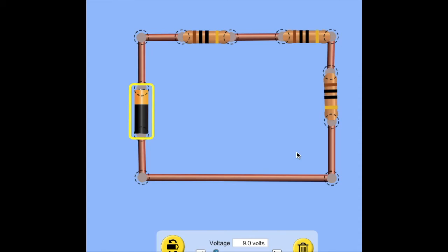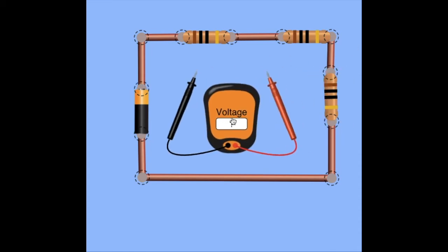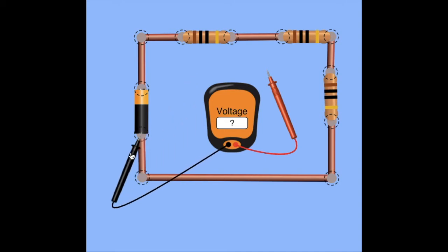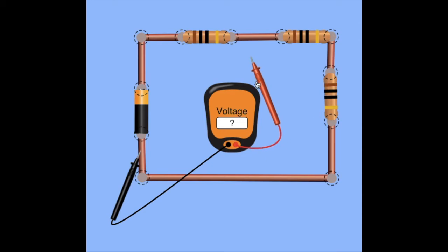Okay, what we have here is a battery in series with 3 resistors. And the battery is a 9-volt battery. Now I'm going to take the voltage probe and I put the black, which is the reference probe, there. And this says that the red probe is 9 volts higher than the black probe. So the delta V, the difference in voltage across, is 9 volts, with that red being the higher side, the higher potential difference. So that gives us the voltage across there.